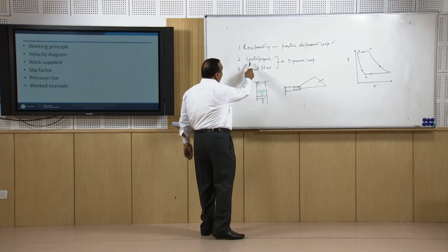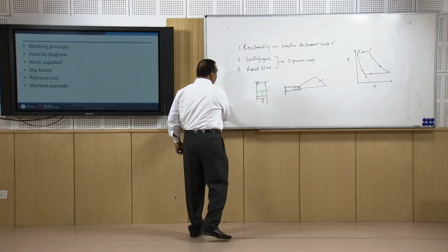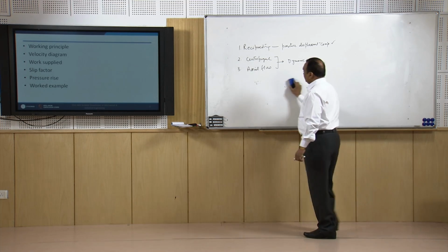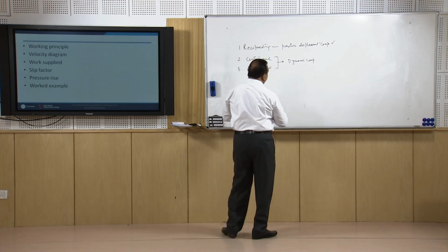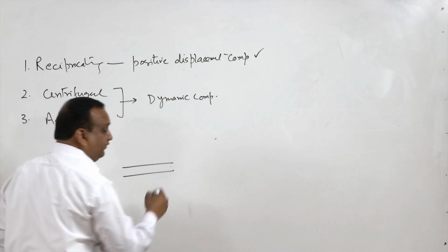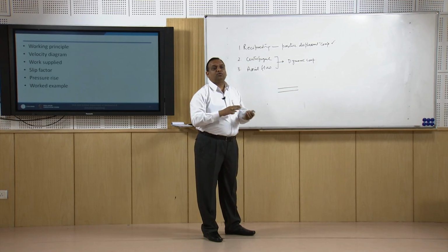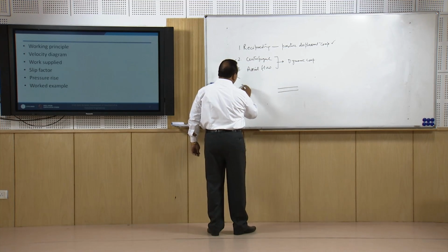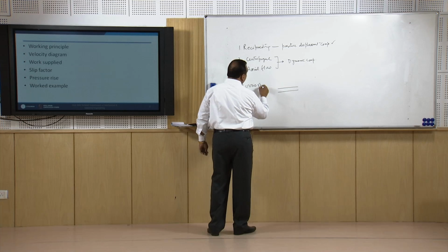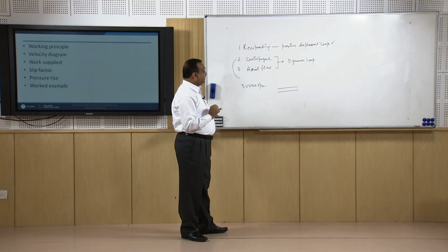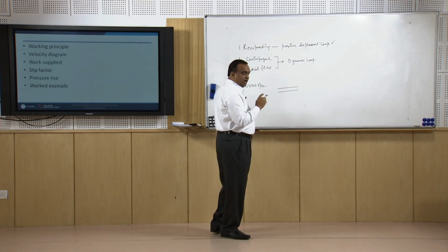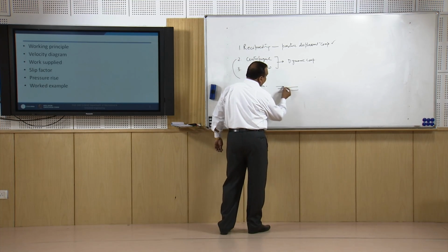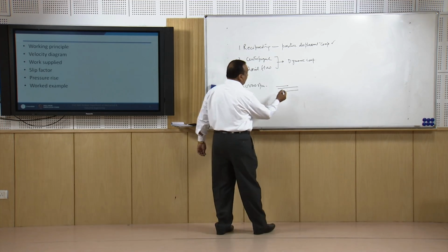Now, if you take the centrifugal compressor, it is a rotodynamic machine. It is a rotary compressor. In a rotary compressor, there is a shaft. On the shaft, an impeller is fixed and there is a housing. So, there is no unbalanced force. So, these types of compressors can go up to say 30,000 RPM, right. In centrifugal compressors, because I will explain the mechanism later on, there is an axial entry of air and radial release.